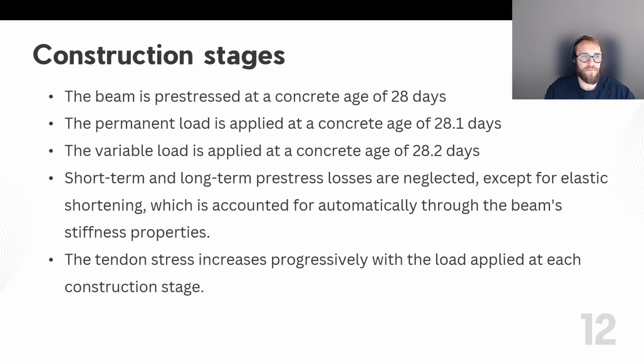There is happening short-term and long-term losses. For concrete, if you pre-stress it, and also for reinforced concrete, there is short-term and long-term behavior of the concrete. So once there are pre-stressed tendons, we are also accounting for the losses on the tendons that are later projected to some staged behavior of the concrete, because in the relevant time there will be different creep and shrinkage, different losses, so the beam will behave differently because the stress is decreasing because of the losses.